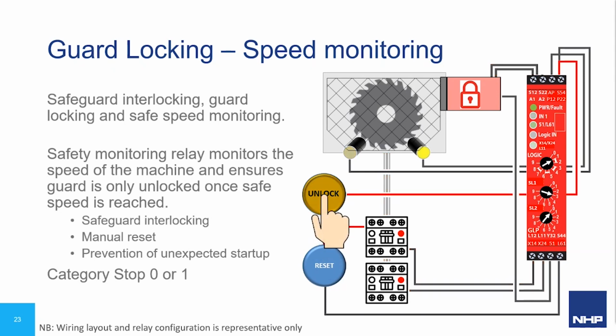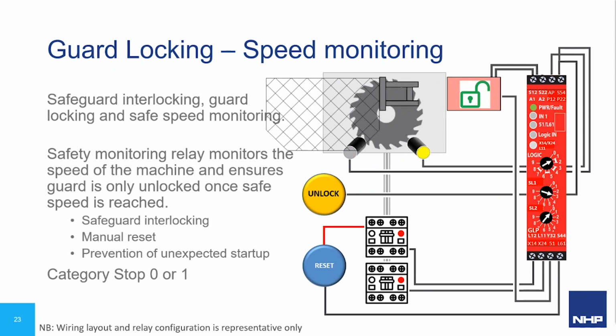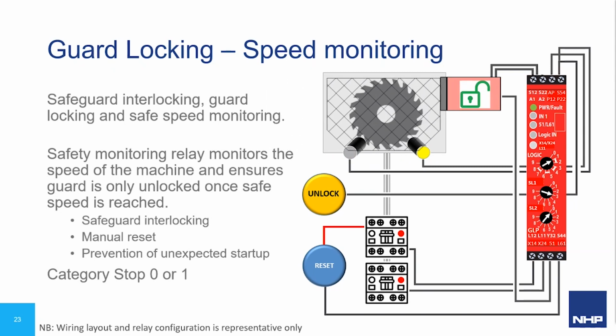If one of the sensors fails or is removed from the load, the signal will go low. If the safety monitoring relay is expecting at least one signal to be high at any given time, by the time the second sensor detects the notch, both signals will have gone low, and thus the safety monitoring relay trips on an input fault.